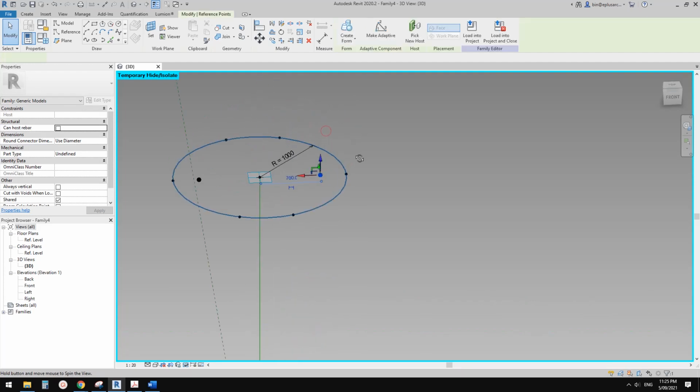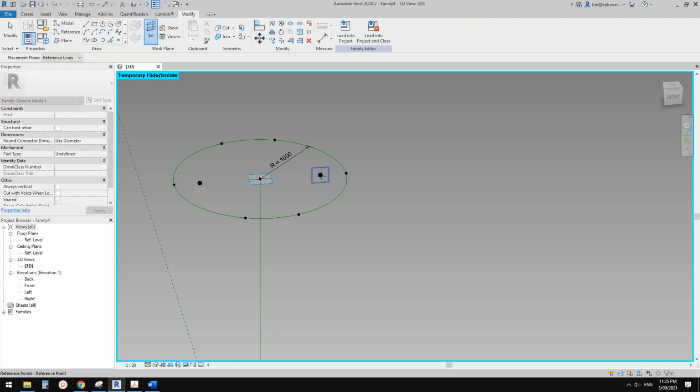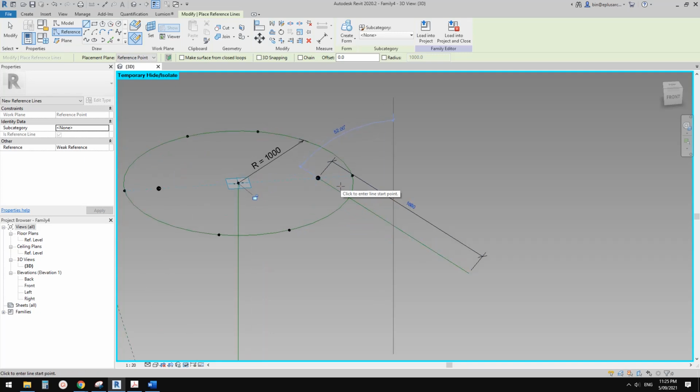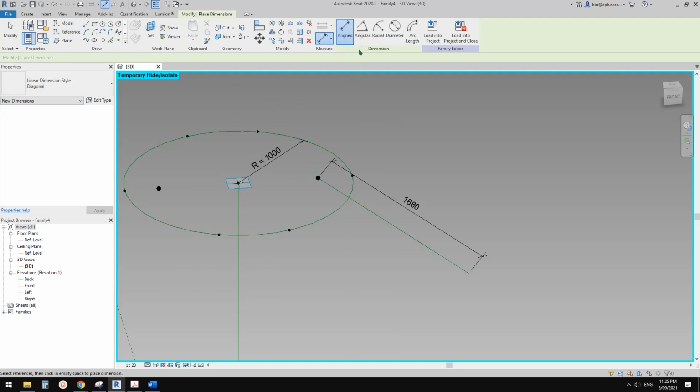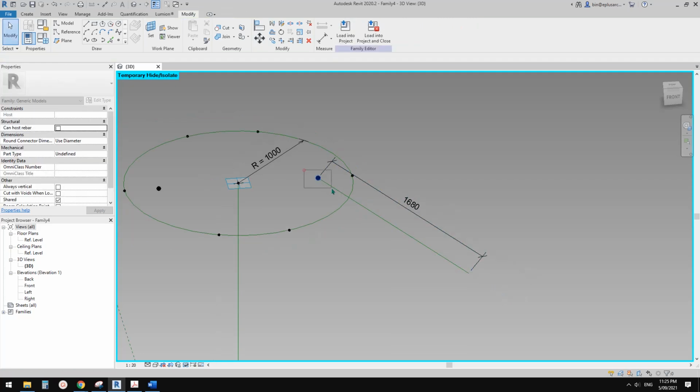and okay, so it's finished here, and then we need another three up here, so it will be exactly the same. So reference, draw work plane, set work plane, tab, select the vertical work plane, go down, length, and then I think the work plane is still on the vertical, so let's directly do the dimension angle here and try to, looks like we can't pick the, we need to show the work plane.